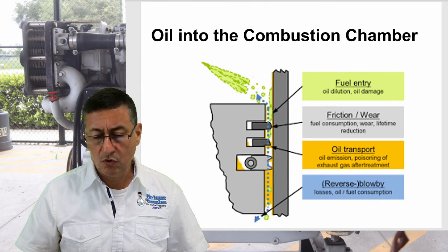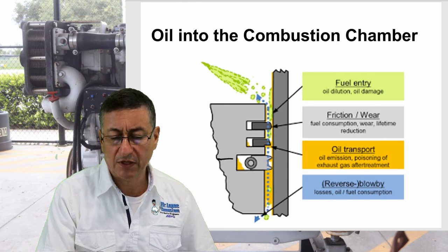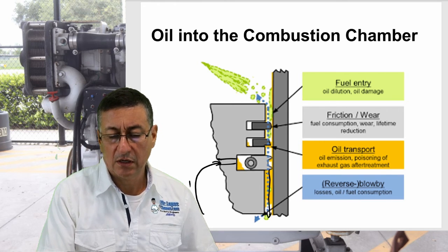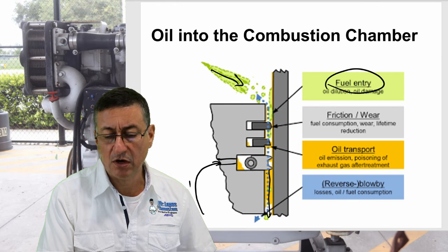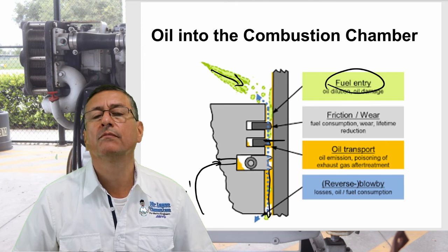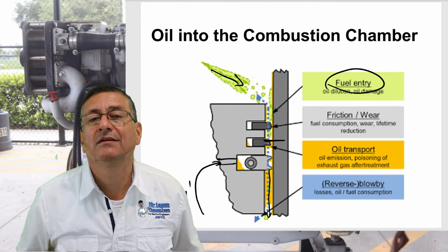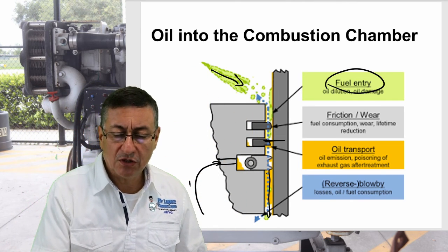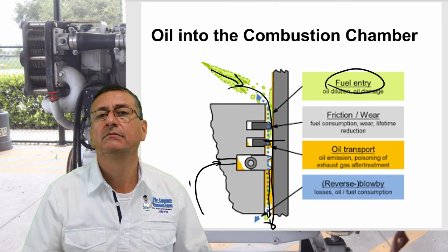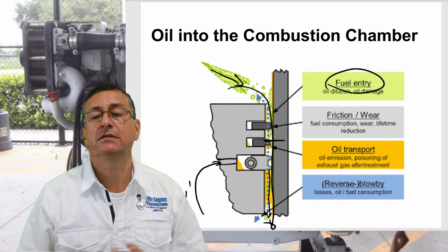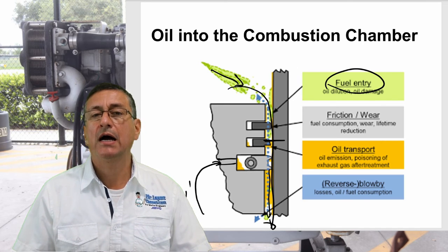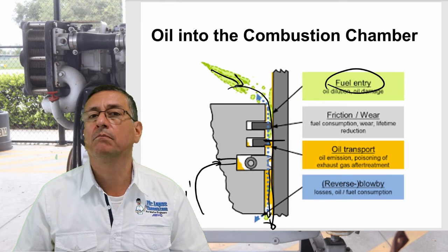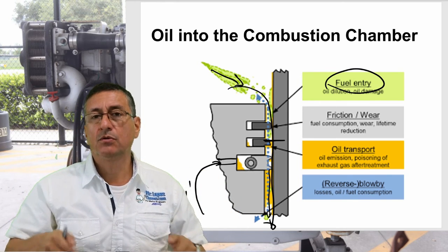Don't forget, this is another good example. The oil penetrates here. You have the drill here. The oil penetrates over there. This is oil, and the oil goes down. On the top rings, the fuel and the air enter and penetrate only until the second ring. Of course, if the rings are broken, you have low compression because the air and the fuel pass directly to the bottom. Those are extreme cases. In regular operation, if the piston rings and the cylinder wall are in good condition, the air and the fuel never pass into the bottom.